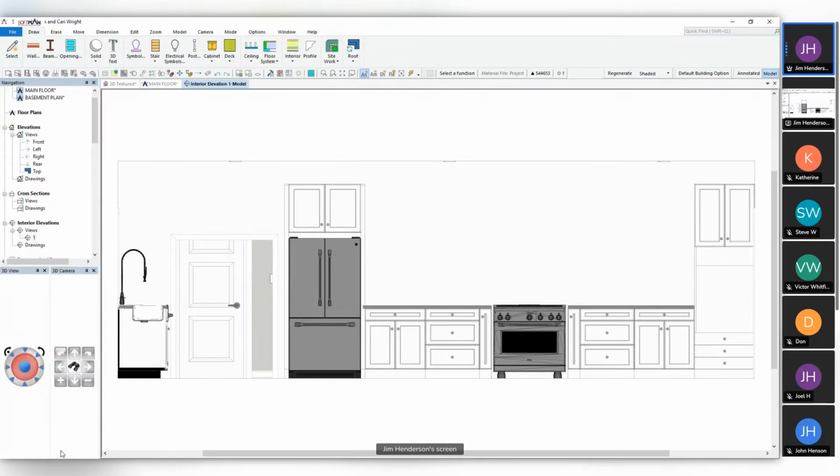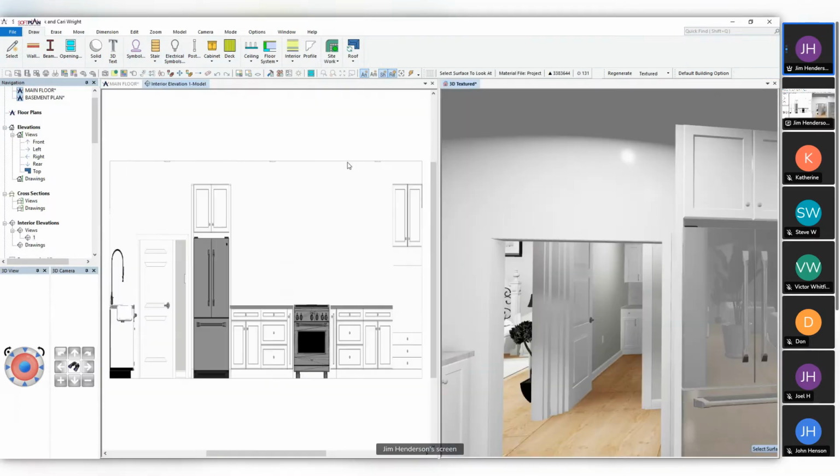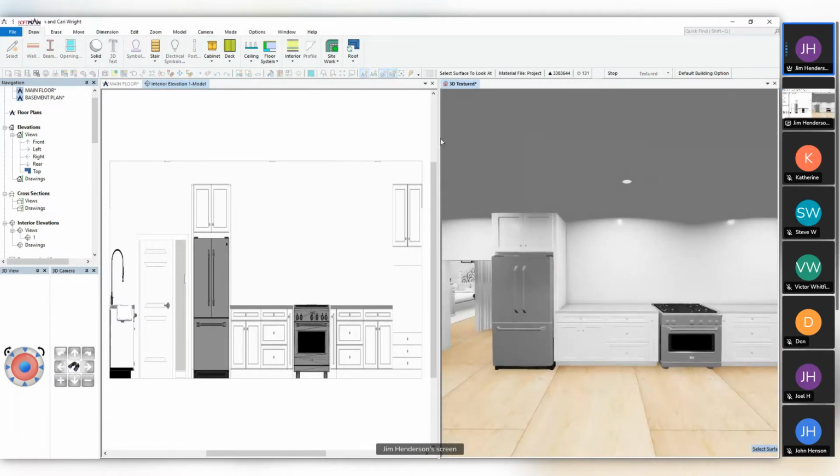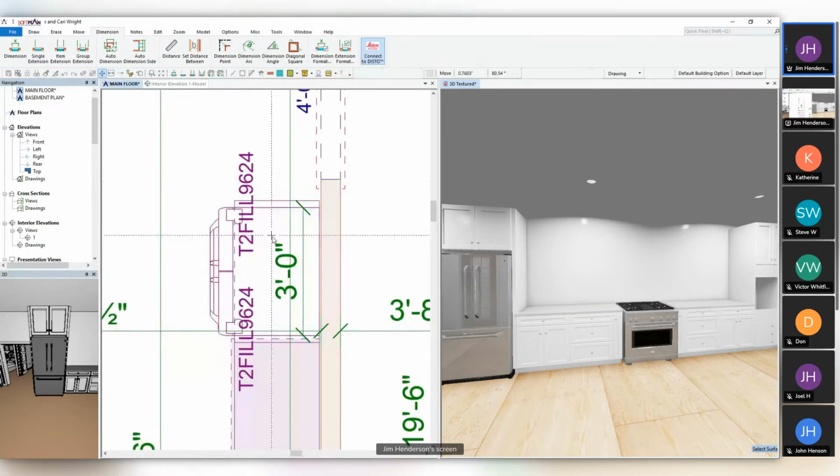And so carrying on from this, I can either draw in the elevation view or I can draw in the plan view and have it update as we go. So as I'm doing this, I'm going to break this into a new vertical tab group. So what you're going to see, I just did a right click and pick new vertical tab group, and it's actually opening up, if you will, on the right hand side, my three-dimensional model to go with my floor plan over here.